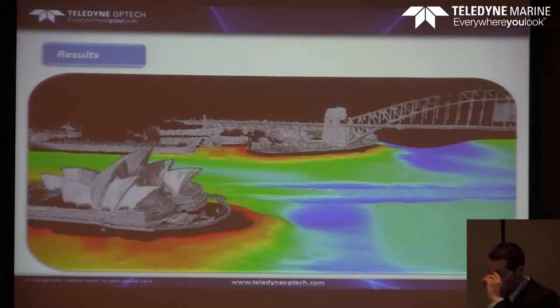Now, the result was actually amazing. We got basically the whole rock, so all the harbor. What you can see, and something that I didn't mention before, is that you always see a little bit of gap between the laser scanner and the bathymetry data. In this case, we used, if I'm not wrong, the SeaBat P50. So the aperture is 165 degrees. So whenever you do the bathymetry, you just miss some data on top.